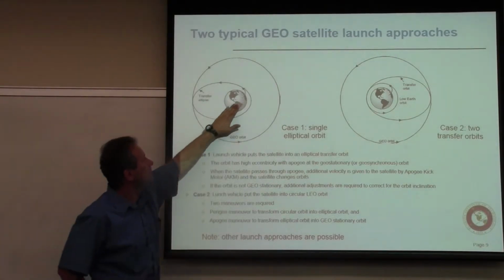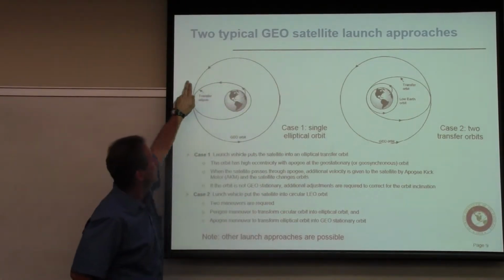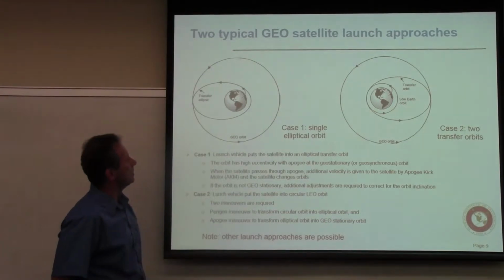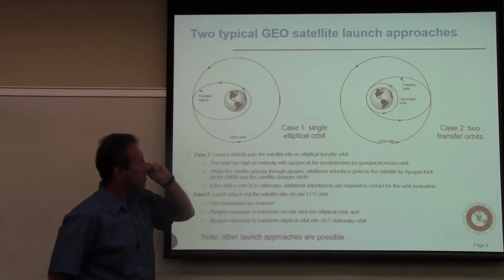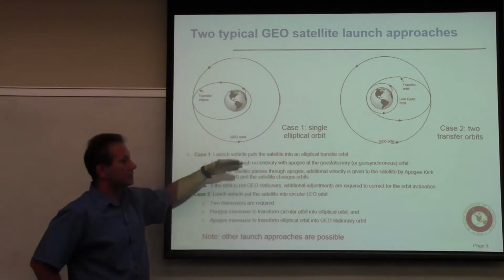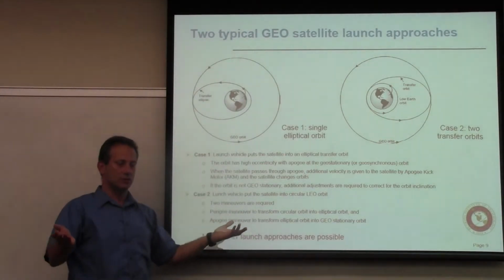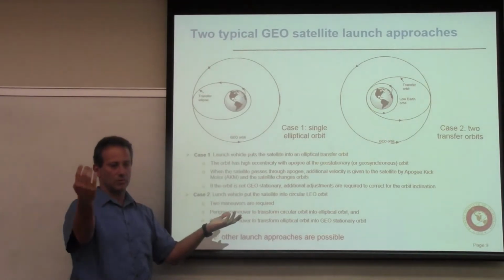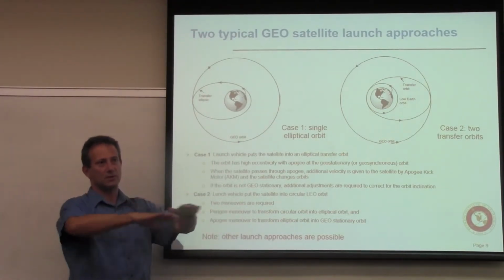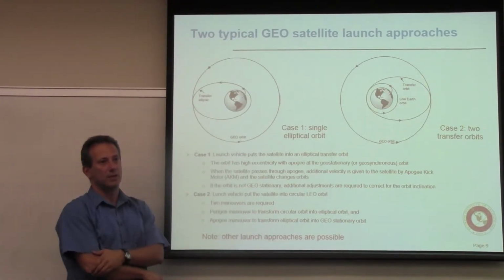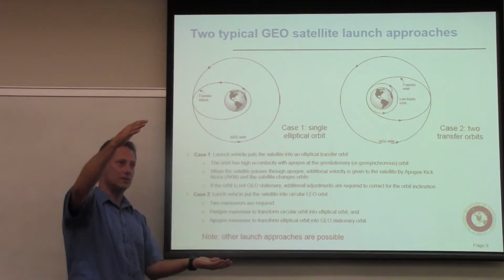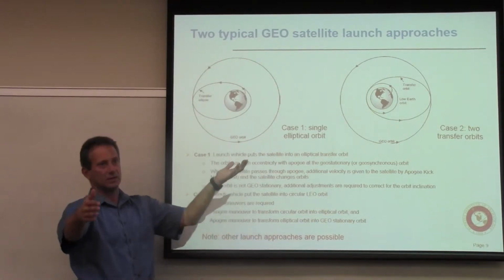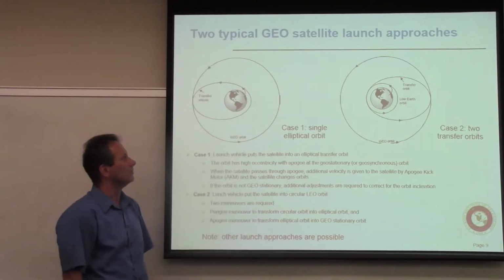So that's one way of doing it. You have the initial stage where you blow through the atmosphere, you have your transfer orbit, and then you have your final orbit. Now, if you launch from the equator, let's say when you do the geostationary launch, then your orbit is within the equatorial plane. If you launch from other locations, you can only put a satellite in inclined orbits, so there will be another maneuver that will move the inclination.